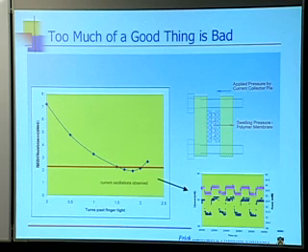And that's a good thing to happen because you get an improved membrane electrode interface by doing that. And you can enhance that process by starting to tighten down those bolts so that you don't need as much swelling to get good contact between the membrane and the electrode.